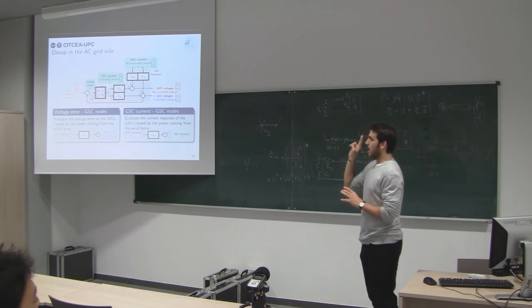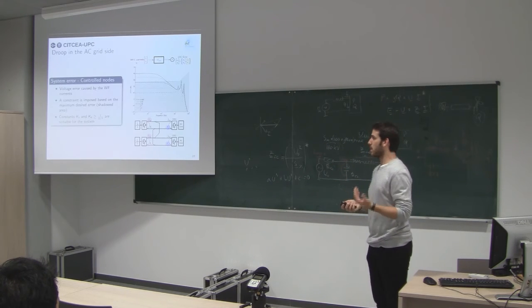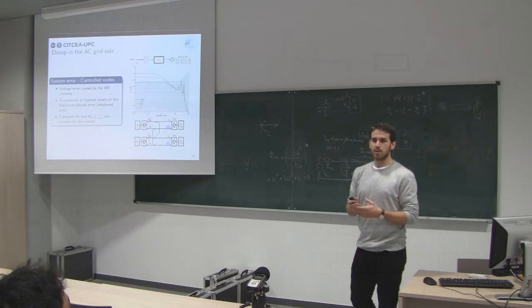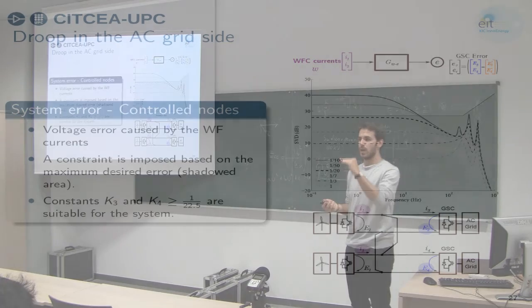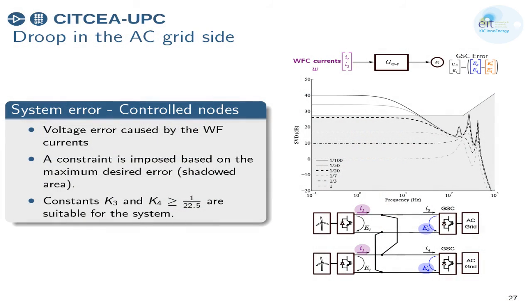Based on that, I focused on these two transfer functions, and I applied something like a Bode diagram, but for multivariable systems. A Bode diagram gives you the gain of the system. With multivariable systems, you have vectors, so there are directions of inputs and directions of outputs. If you excite the system with 400 and 400, it is not exactly the same as exciting the system with 400 and 0.